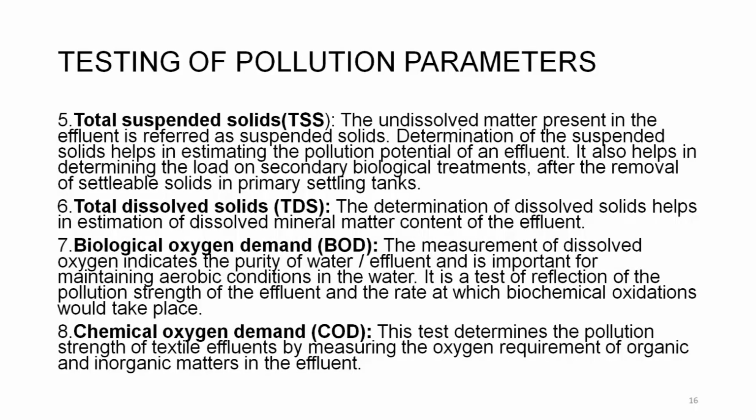Total dissolved solids. The determination of dissolved solids helps in estimation of the dissolved minerals present in the effluent. Biological oxygen demand, BOD. The measurement of dissolved oxygen indicates the purity of water or the effluent and is important for maintaining aerobic conditions in the water.